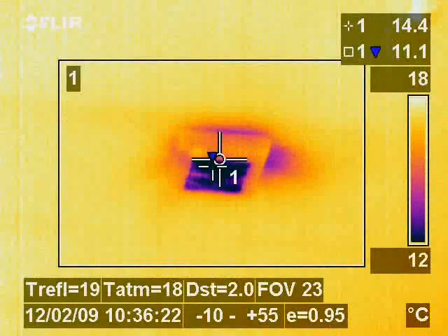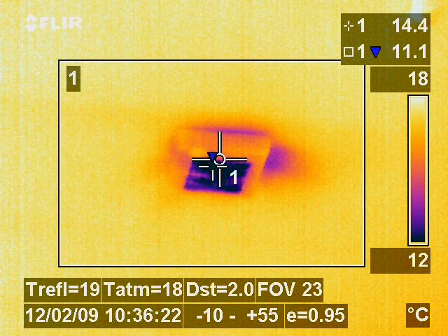The image here is of a roof vent in the utility room of a dwelling house which was retrofitted after the house had been completed. The thermal fault is consistent with a lot of retrofitted vents and electrical outlets where insulation had been removed from the ceiling in order to actually fit the vent. The insulation hadn't been put back in place and no correct seal had been made between the vent and the ceiling. This left a path for cold air to come from the ceiling space between the floors to come into the room.